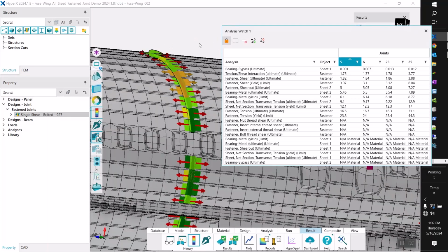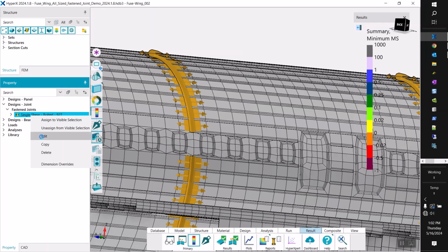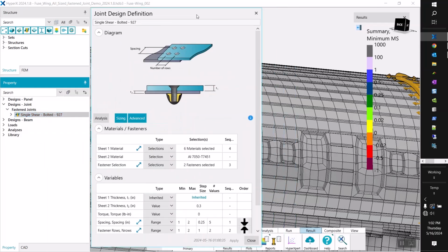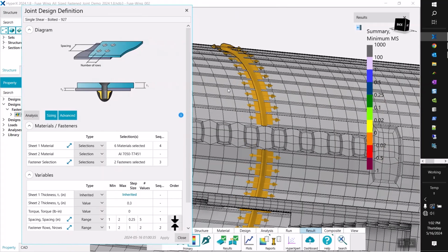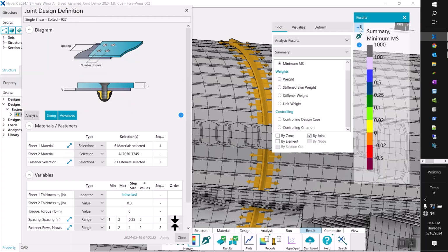And so, yeah, you still have all the reporting capability for edge joints that you do for panels and beams, as well as the ability to locally size these in such a way that you can size the joint with a coarse finite element model, and you can override the thicknesses of the edge bands, and then you can extract the corresponding sizing results.